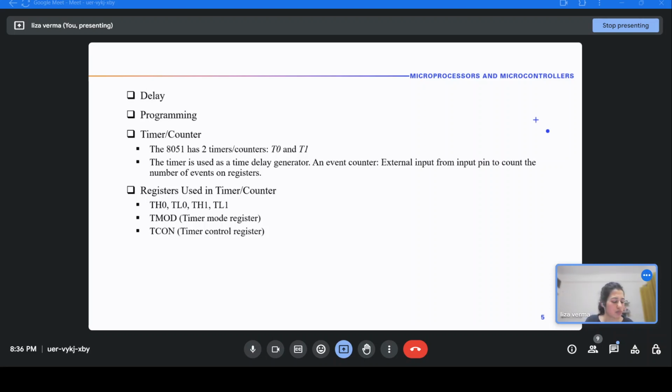Okay, so just for the sake of completing it, M0 is a 13-bit timer counter. It requires 8 bits of THX, X being 0 or 1 depending on timer 0 or timer 1, and 5 bits of TLX. Right? M0 is very useful in serial communication, which I think is next week or the week after. M1 is a normal 16-bit timer counter.